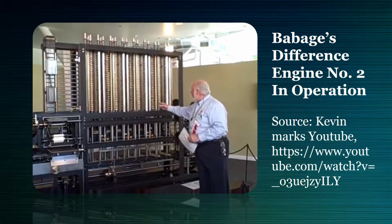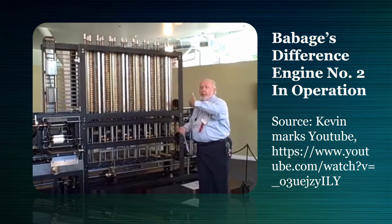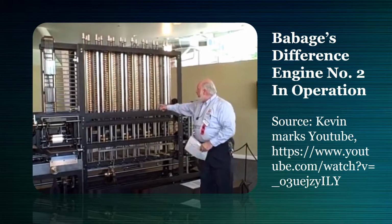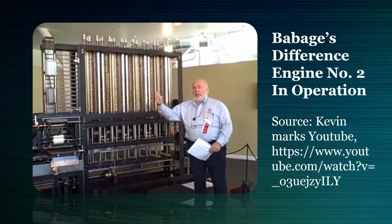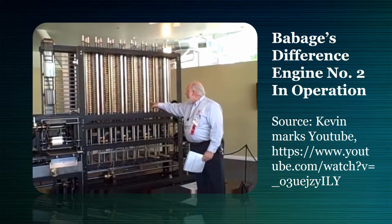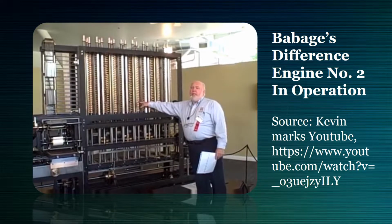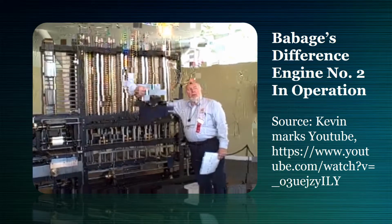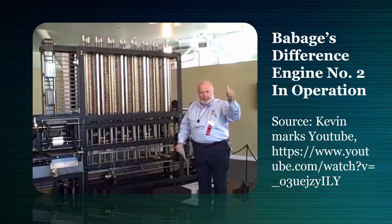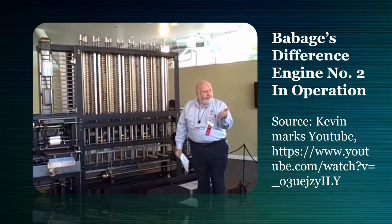And as it turns counterclockwise, the gear in between will turn 8 positions in a clockwise direction. It's engaged to the even gear, which turns counterclockwise and turns 8 positions. But when the even turns 8 positions, its numbers are on there clockwise. Turning them counterclockwise causes it to go 1, 2, 3, 4, 5, 6, 7, 8. It counts up.